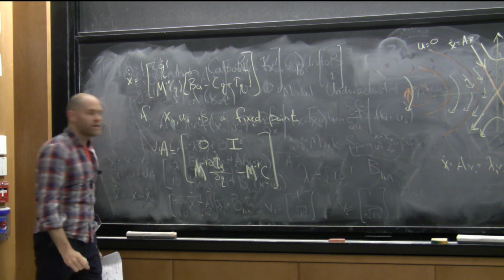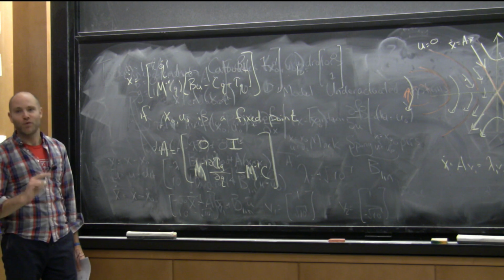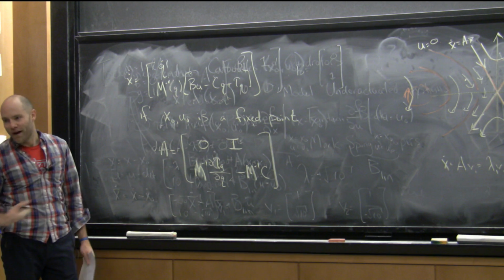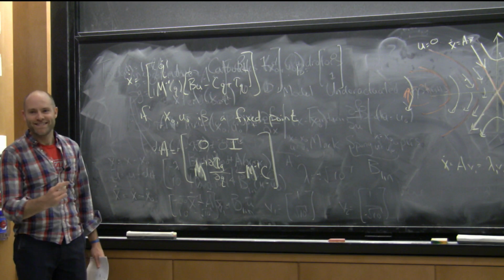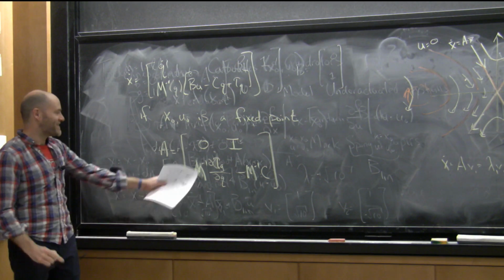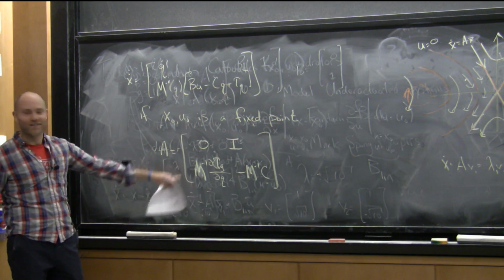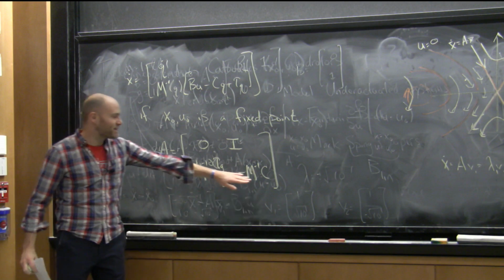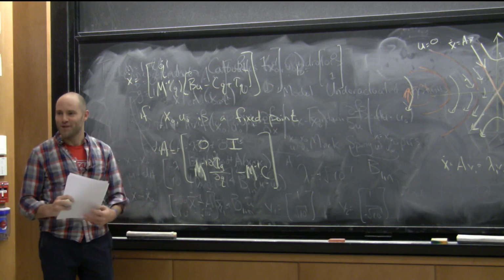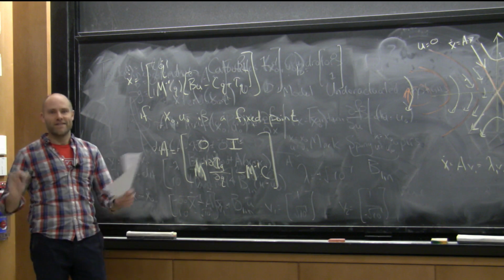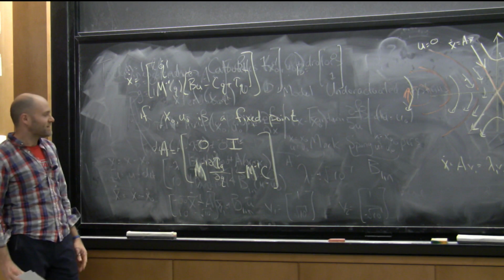And this turns out to be really easy. And so in MATLAB, you can only call LQR of A, B, Q, R. But in Drake, you can call LQR of robot, comma Q, R. And it just does this for you. Yay! I mean, that's a lot of work, right? Not just because of this, but because that means you had to be able to auto-diff through your equations of motion of your robot, for arbitrary robots, to take gradients of full robot equations and do it efficiently and everything.